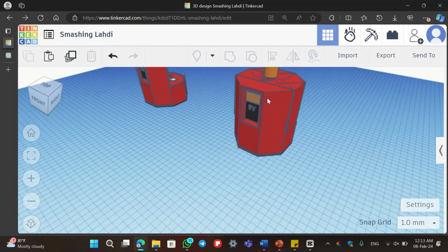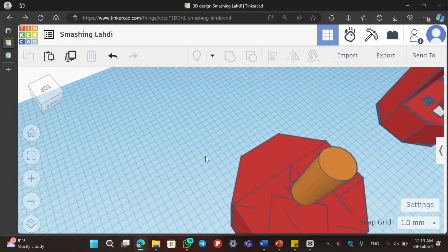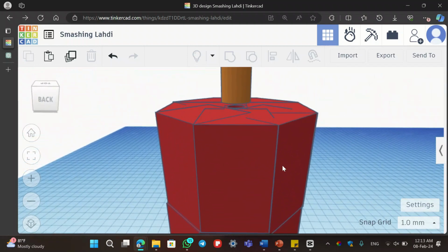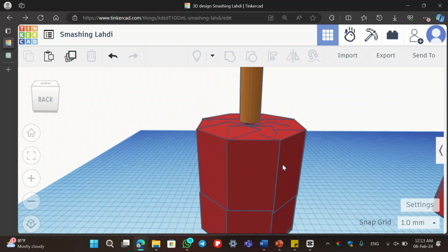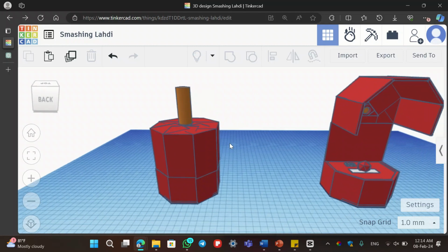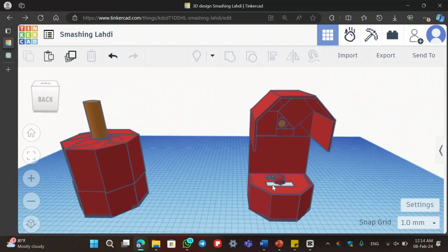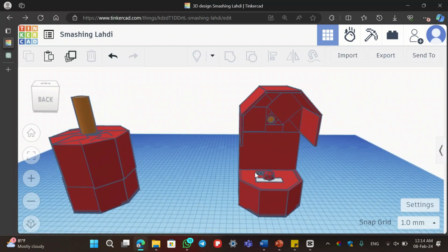At the back we have 9V batteries. This experiment needs to be conducted in low intensity of light to avoid the sensor saturating. That's why the box needs to be closed before starting the experiment. Then the laser will be transmitted to the CCD sensor. When the sensor senses light, the output voltage will become high, otherwise the output will be low.